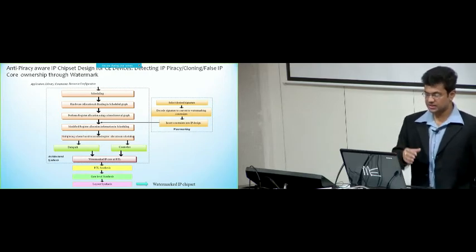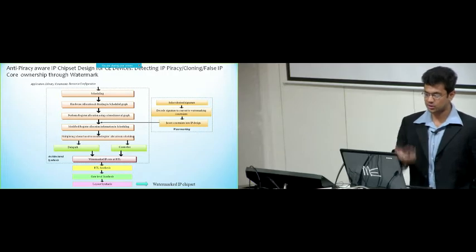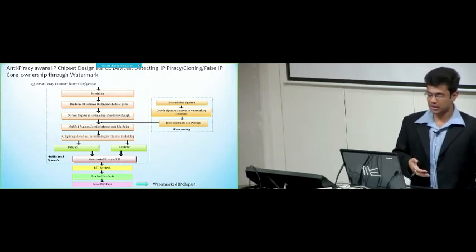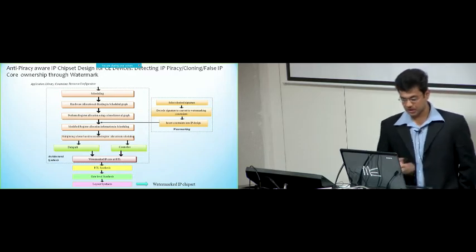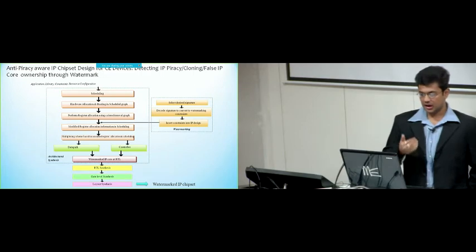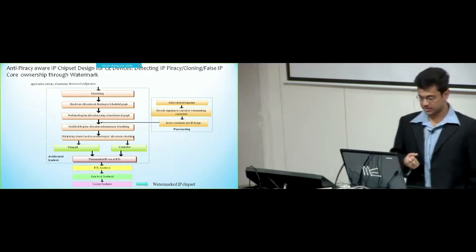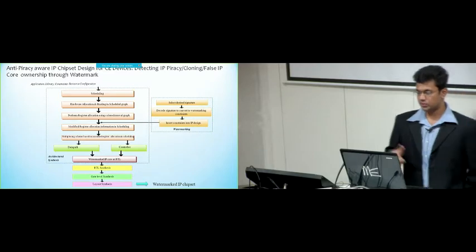Now, this design is certainly anti-piracy aware, as any sort of piracy or cloning or any other false claim of ownership an attacker tries to make can easily be detected. Finally, this watermarked IP at the RTL can be RTL synthesized, followed by gate level synthesis and then layout synthesis, and this final form is called the watermarked IP chipset.